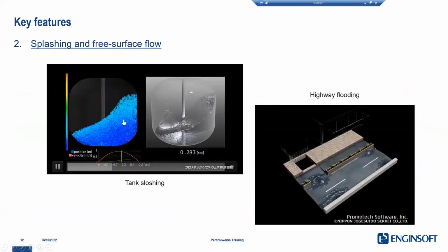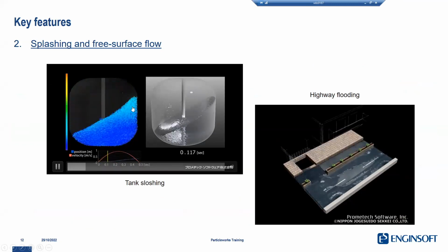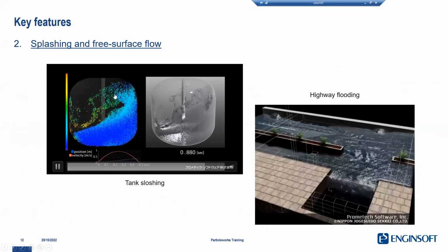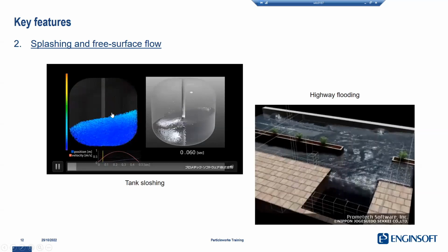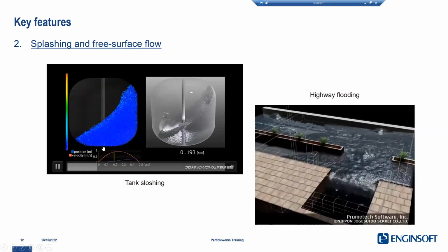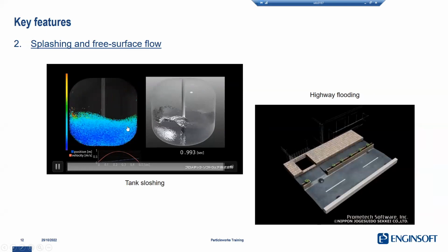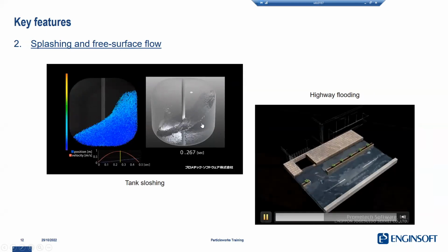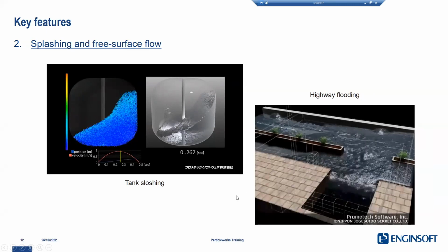Here is a little bit of an example of the type of flow that we might want to analyze. As you can see here, we have large deformation of the free surface. This type of phenomena are very difficult to capture with a conventional method, because a priori we don't know where the flow will go, basically, okay? So it's very difficult to prepare a mesh that is correctly discretizing in the region where we need the splashing phenomena.